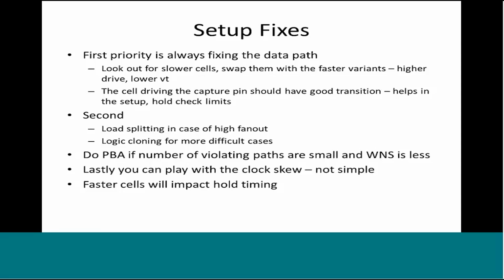This is the analysis that you can do within PT itself, but the real results will only come when these ECOs are implemented in the backend and new parasitics are generated. So whatever analysis I am talking about is at best an estimation, although most of the time it will work as it is. If PrimeTime shows that the path delay has improved, in the majority of cases the delay will improve when the actual network comes up.